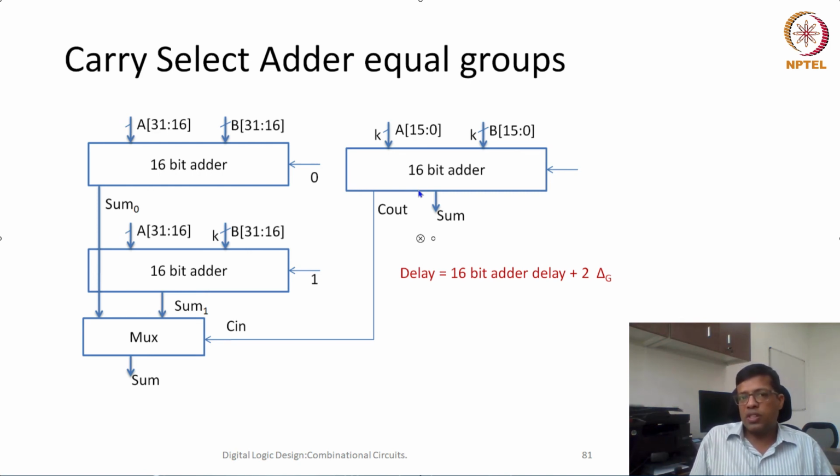One group was 7, then 6, then 5, then 4, then 3. If the size of the group is variable, then using some other effective adder like carry look ahead adder or parallel prefix adders will create some sort of confusion. We are not sure what delay would actually match the two parts.